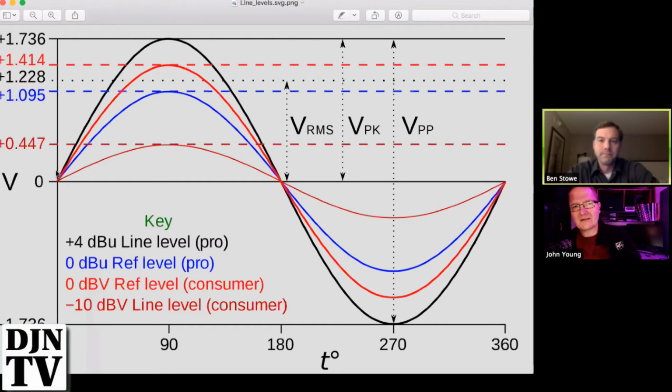I'm just kind of thinking, because we've got a popular mixer that we've talked about on a lot of the shows, the little tiny Numark DJ2GO2. Nice little unit that you can use for performance, but it has a 1/8 inch jack as its output, which would be consumer level. Correct. So to get that to our speakers in the best way possible, you mentioned that consumer level wire shouldn't be over 6 feet long. So really to do that right, a person should be running it into some sort of a mixing board to get you from point A to point B, switching it over to that balanced signal. Am I reading that right?